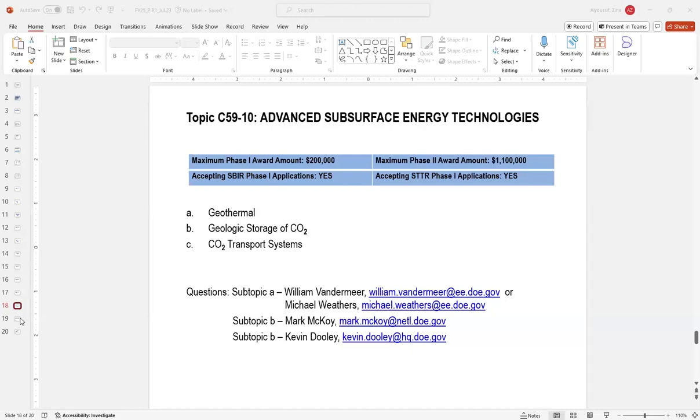Some of these impurities range from oxygen, sulfur oxides, nitrogen oxides, hydrogen, among others. For this particular topic, we're looking at oxygen, because it can lead to oxidation of metal surfaces, pipeline corrosion, and the formation of solids in transportation systems and potentially the downstream surface and subsurface.